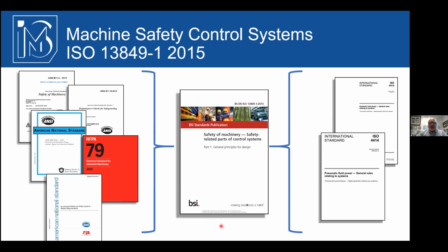So if you're in a company and you hear people talking about the SIL rating, and we're talking about machines versus process control, like a continuous or batch process, that's where SIL has migrated to. We still use SIL because there's still electronics doing process control and process safety. It's typically only going to be electrical electronic systems, whereas in machine safety, we're using hydraulics, pneumatics, and electric systems. So you have to use 13849 to address all of that.